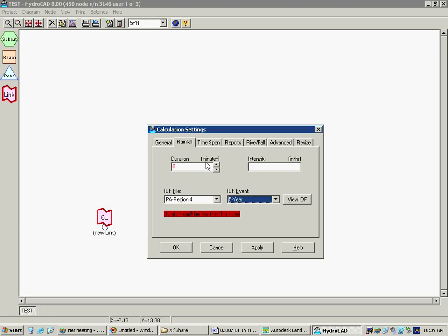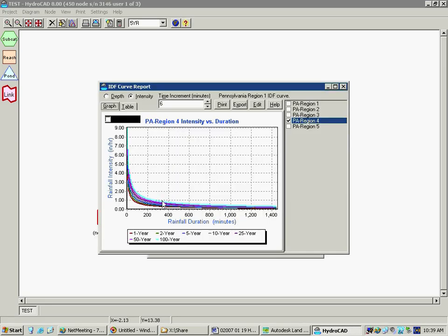Okay, this is where it starts to get complicated, because if we had one drainage area and one basin, just like you would model with VT Push'em, you would set the duration to equal the TC of your drainage area. And I don't recall, is it 15 point some minutes? All right, so we'll call it 15 minutes, and that automatically pops up an intensity that is dependent directly on the IDF curve that we have. And you can see the IDF curves here if you want to.